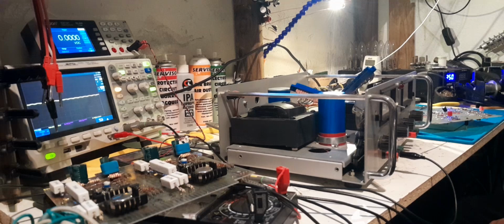the old LM301s were pretty heavily compensated. I would imagine the slew rate of these, the way they are running open uncompensated, would be faster currently.